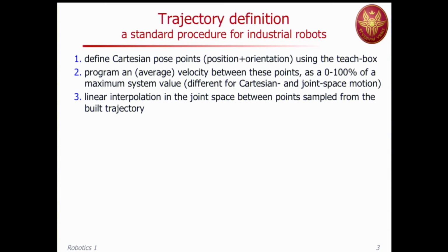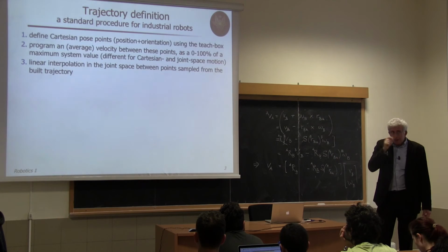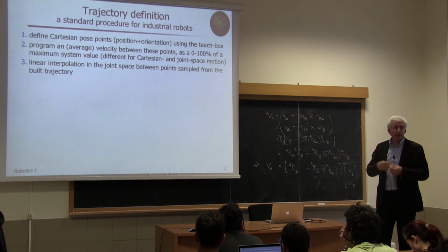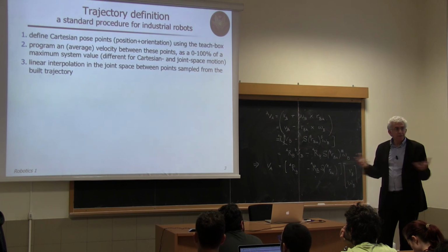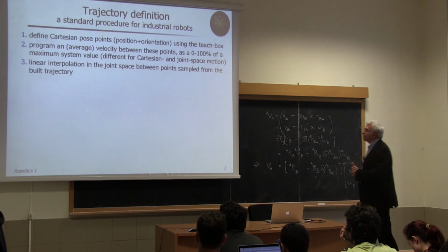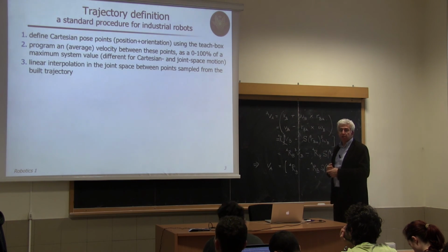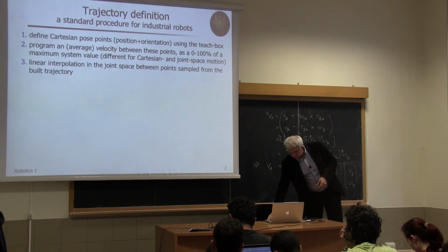Now, once this is built, there's a micro-interpolator inside the controller that generates a sequence out of this general description, very qualitative, with apparently no mathematics, so as to have the references in the joint space for the actuators and for the controllers.